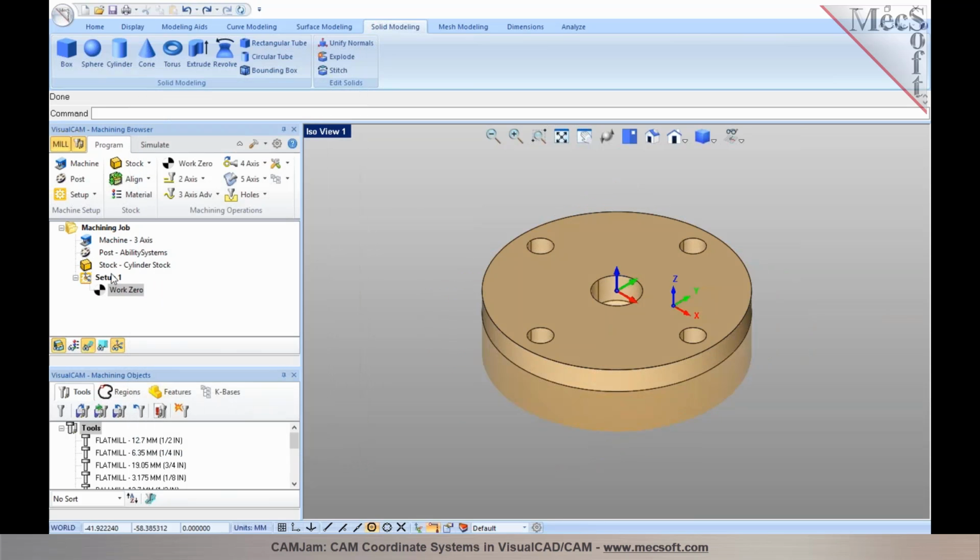Now once you establish that, you'll notice that your machining coordinate system origin is offset from the world coordinate system origin. So in terms of the design coordinate system, your XY00 is right where it is labeled with these three XYZ markers in here. And the origin for machining is established at the center of the part. So all your tool paths that you generate or compute would be based off the machining coordinate system origin.